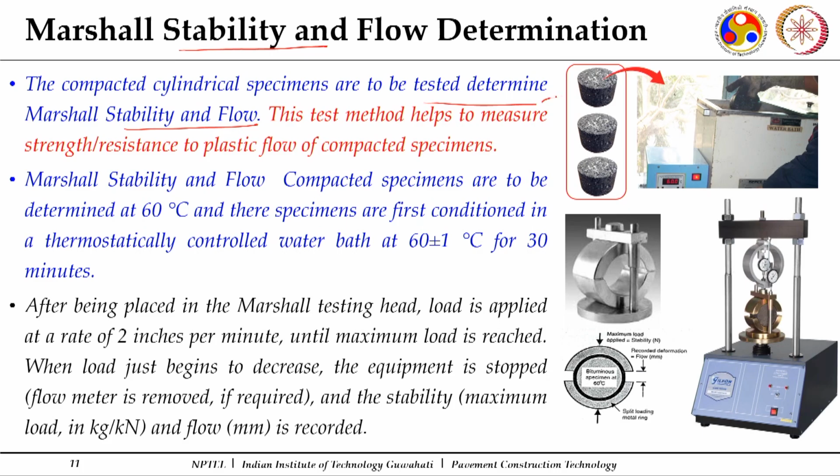They are to be first brought to the test temperature, which is 60 degrees. For that they are kept in a water bath for 30 minutes. Then they are transferred to this Marshall stability mold. There the load is applied at a rate of 2 inches per minute, and simultaneously the deformation, the flow, is measured. So, you have the load measurement setup, and you have the deformation measurement setup there.